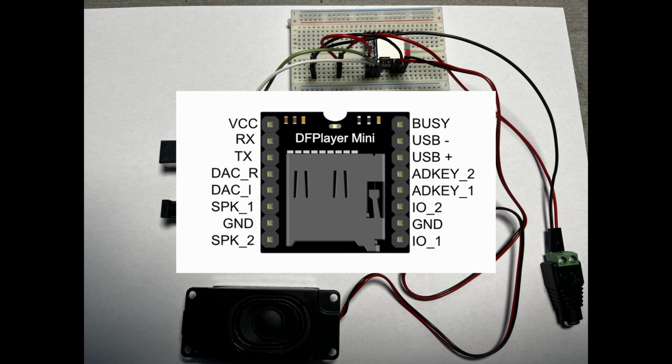There are many options out in the market on how to play sound. For availability reasons and simplicity reasons, I decided to add the DFPlayer Mini to my setup, and this video will cover how to physically connect the DFPlayer to your Arduino and what changes you need to apply in Bottango to play the sounds stored on the SD card which is inside the DFPlayer.